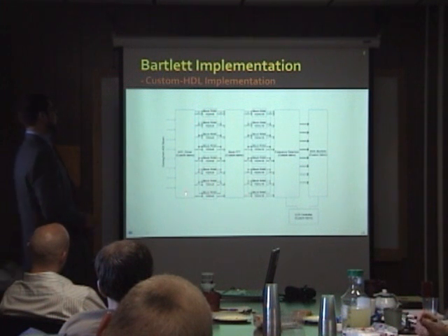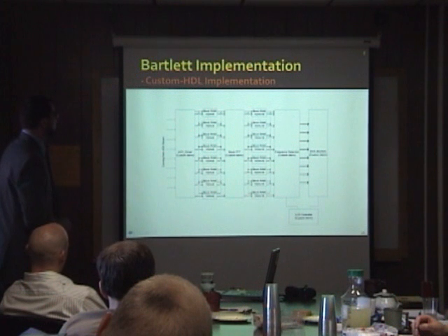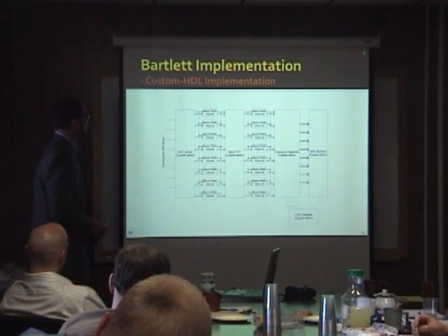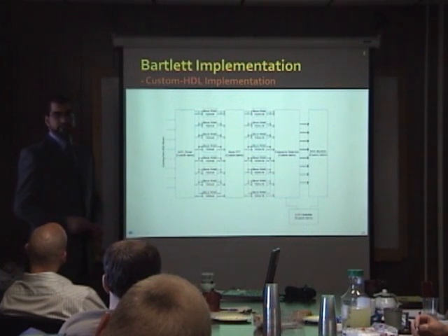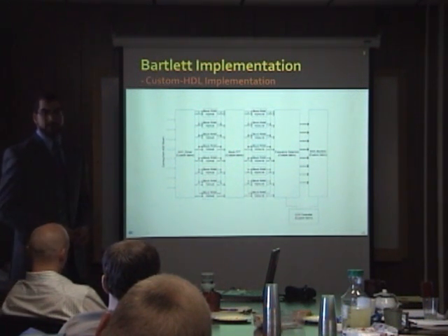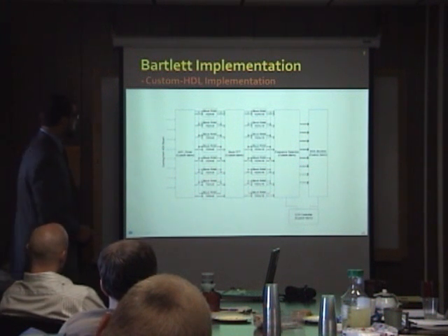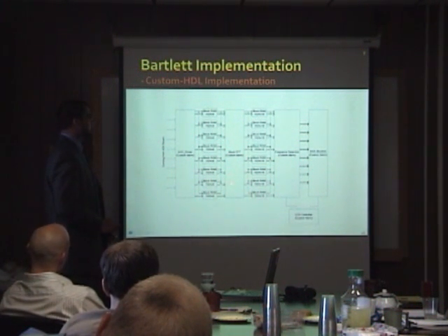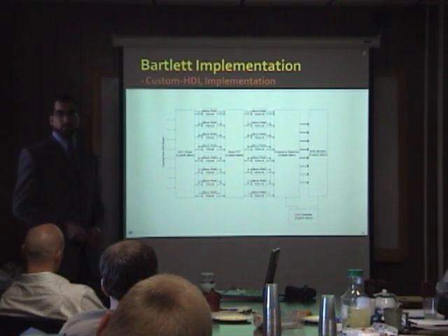a block, 8 block RAMs, one for each channel, and it's 1024 points by 8 bits wide. Once the sampling of the 1024 points that we need to perform the DOA is over, the ADC driver sends a signal to the block FFT in order to start performing the fast Fourier transform. Once that is done, the results are stored in a 1024 by 18 bits wide memory block.